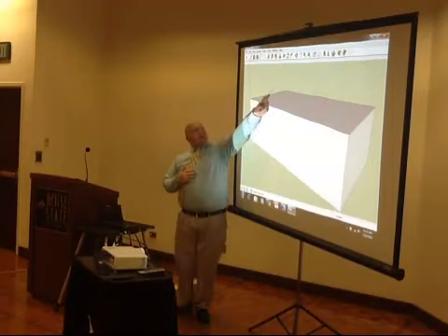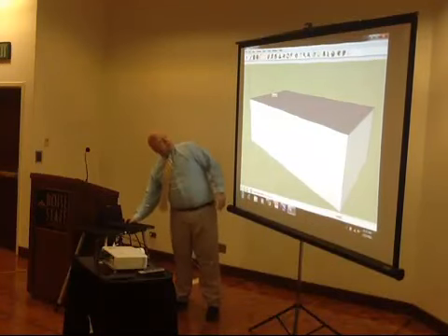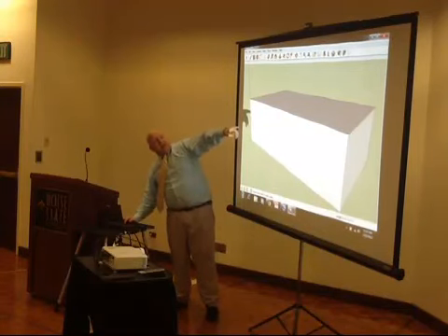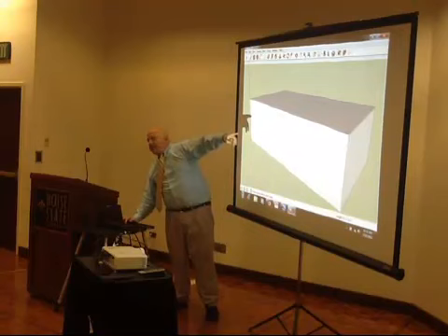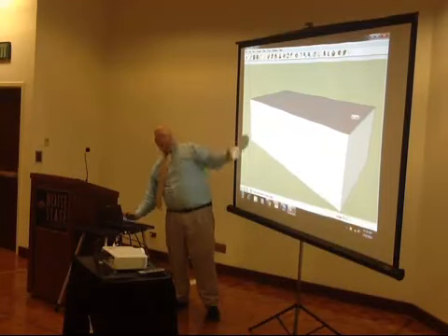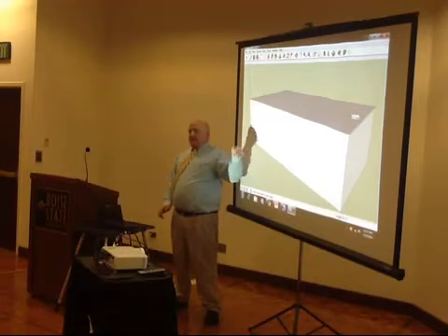So I've got my line tool. I'm on the far edge. I'm going to click once to start, and I'm going to drag all the way across. Now, you can see that I can drag off of that green axis and do any angled line that I want to. But it's almost always a good idea because we started exactly on these axes.